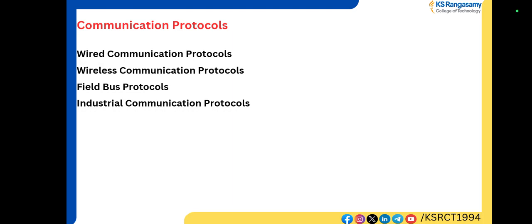In that, we also have to integrate with Wi-Fi and Bluetooth through appropriate hardware and drivers. We can use NI hardware or third-party modules for wireless communication like Zigbee, LoRa, LoRaWAN, whatever the architectures we are having, we can make use of it with LabVIEW. If you want to go with industry standards, LabVIEW as well as the DAQ supports industry standard protocols like Modbus, Profibus, CAN bus, I2C through NI hardware toolkits. It also supports OLE for Process Control, that is OPC, for control system integration.